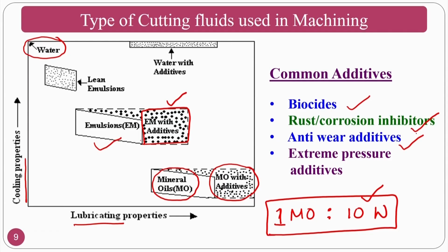You need to have low shear strength materials. Whenever it comes in contact with the two mating surfaces, it should shear easily. Then extreme pressure additives, which you will use so that even at extreme pressure, it should form a layer, so that proper tribological conditions can be maintained.